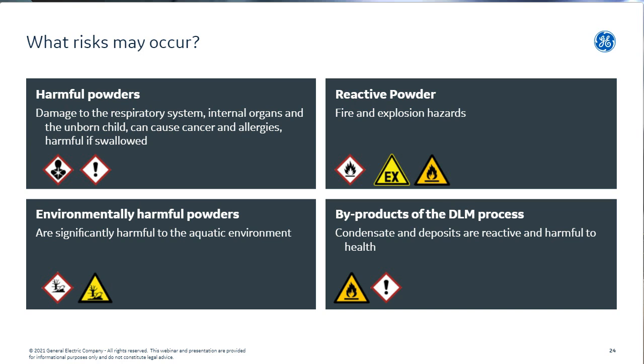Some of the powders have environmental impacts. Nickel powders, as an example, can be very impactful for the environment because nickel is treated as a water-harmful substance. So you need to understand that, and also understand that products from wastewaters may not go into your public sewage system, as an example. The byproducts of the laser printing process, so the process condensate, sludge, dust, fumes, etc., are sometimes a wild mix of the powders themselves and components that react with each other.